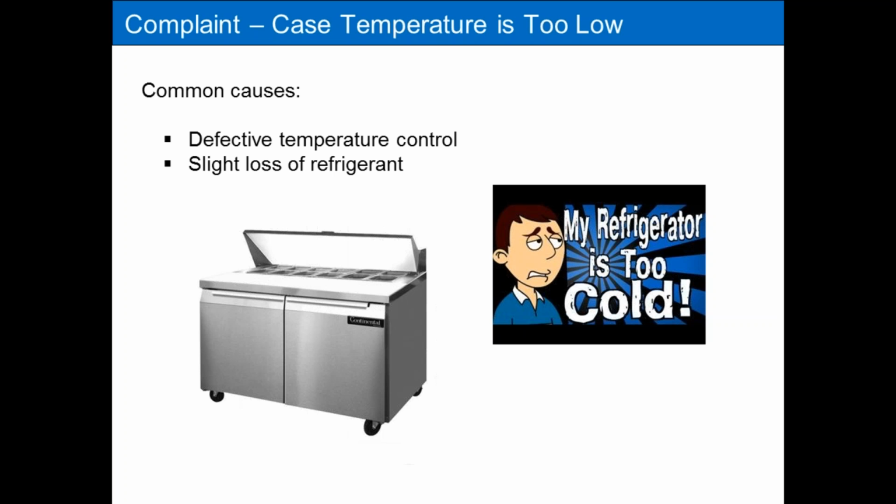Or it could also be a slight loss of refrigerant. A very subtle loss of refrigerant may cause the temperature sensor on the controller not to see the right coil temperature, causing the unit to run longer than it should, dropping the case temperature below normal. So we'll talk about some of those issues as we go through tonight's program.